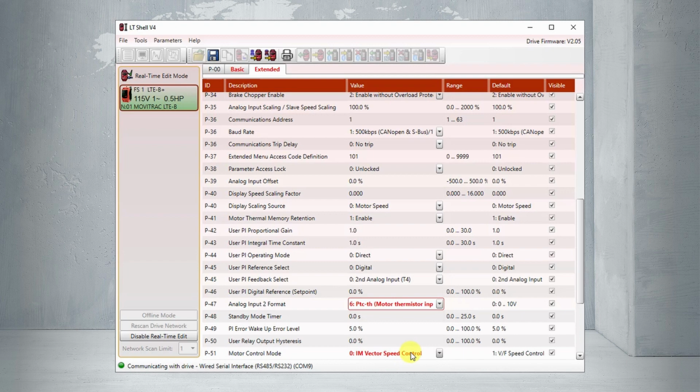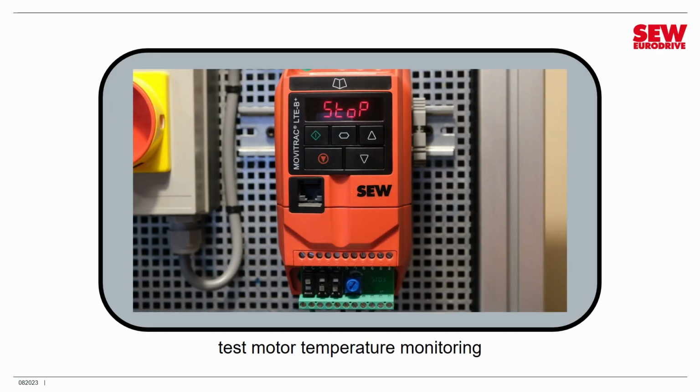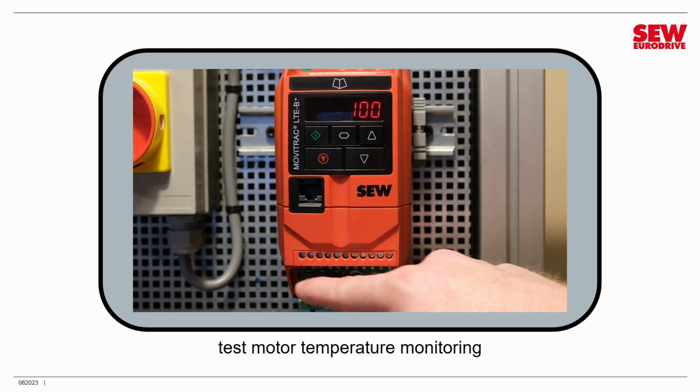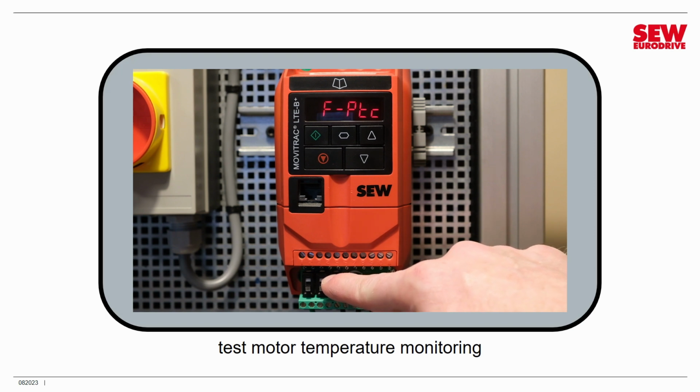So we're going to change that, and now we're going to run our VFD, and we're going to simulate a temperature sensor trip by flipping the switch. Let's try that out. Okay, same situation here. I have the switch connected to DI3 turned on to simulate a temperature sensor that is happy. I'm going to start the drive at a preset speed, and now I'm going to trip DI3 off to simulate a temperature fault, and you can see we get F-PTC.